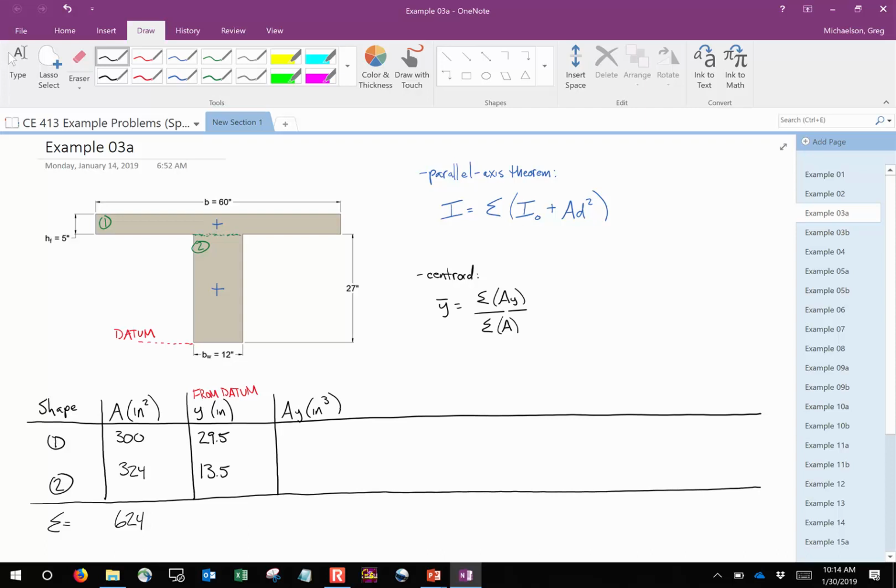So what is A times Y? A times Y. Somebody give me the first one. 8850. And the second one? 4374. Do I have seconds on these? Cool. Now let's add them up. Sum of AY over sum of A. So let's sum them up. Say it again. 13,224. There we go. So what I can then do is I can say now I can compute my centroid.